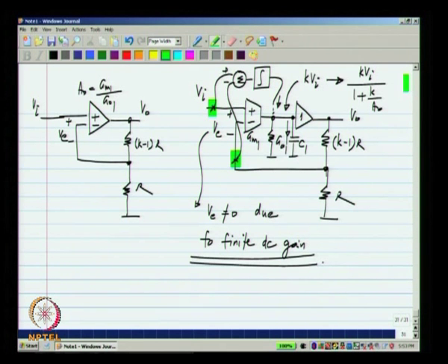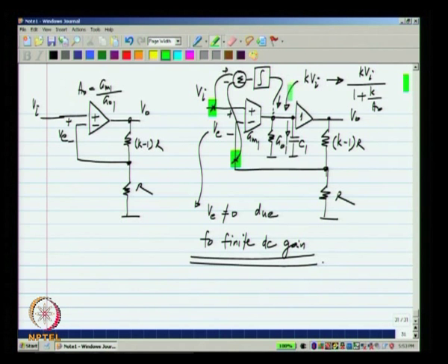Okay. Now, this gives a different class of op amps known as feed forward op amps, which we will discuss in the next class. Now, one other thing that we can guess right away is that we are assuming that the original circuit reaches steady state and based on that steady state error we are doing the integration, but the integration itself is a continuous operation. What this really means is that the second integration that we have here is much slower than the first one. Okay.